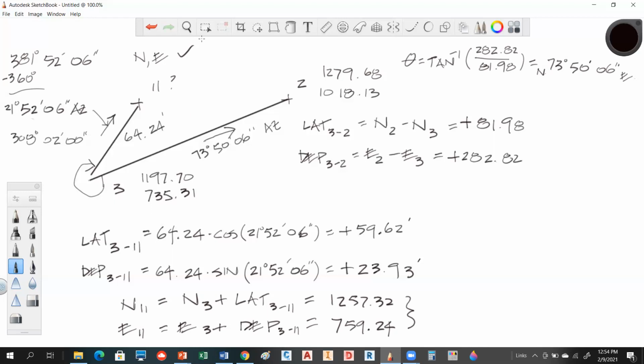So we'll do that. I just wanted to point out something. Look at this equation up here. Latitude is equal to northing minus northing. Notice this is the same equation if I just bring this guy over here. So you can see how these equations are essentially the same. They're just rewritten. Now they're not for the same point, but this is an inverse and this is a direct. That's where it gets the term inverse right there. You're inversing this process. You're changing it up.